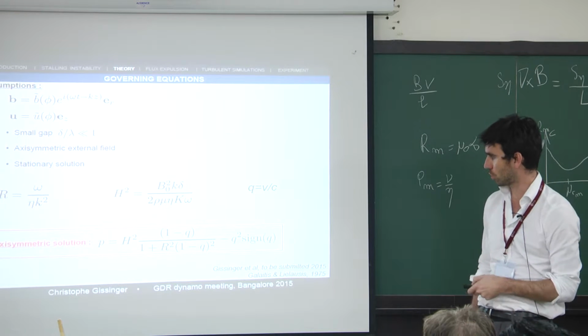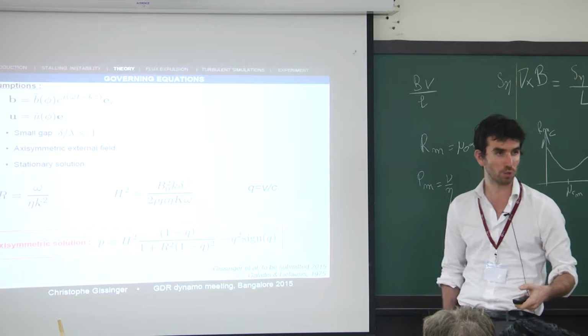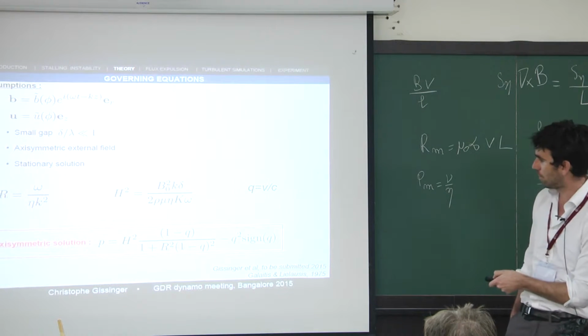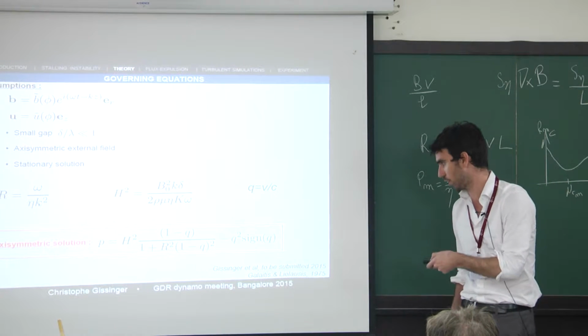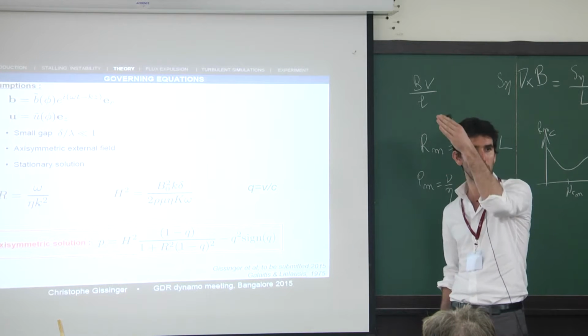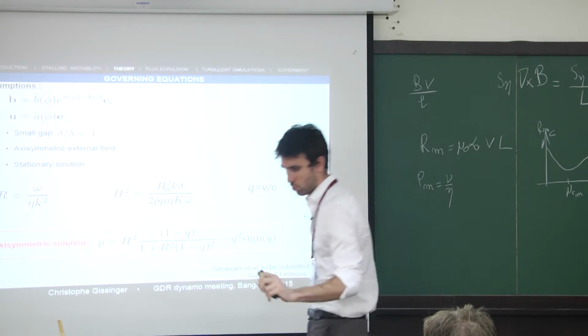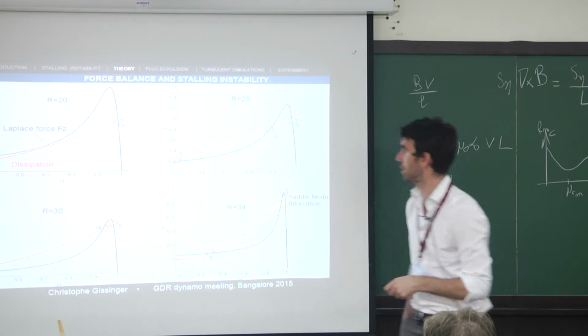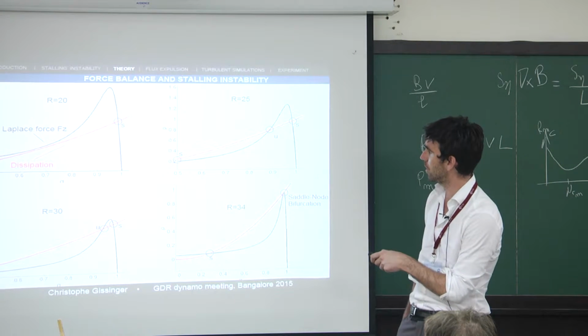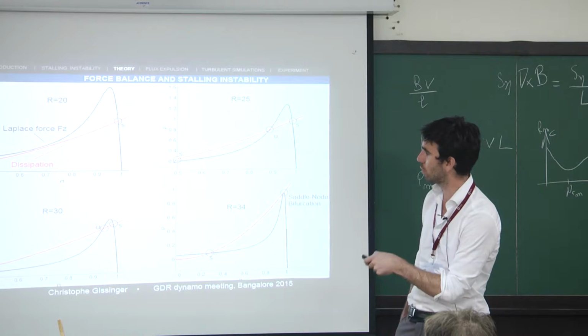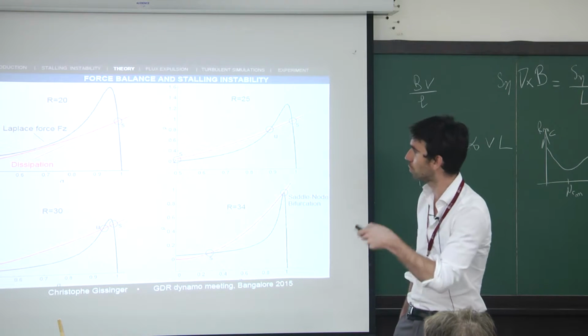The first part is the Lorentz force acting on the fluid, while the second part is the viscous dissipation. I just chose to use a quadratic dissipation. To get an insight of what it is, I just draw this force. The black curve here is the Lorentz force, while the red one is the viscous dissipation, turbulent dissipation or whatever.